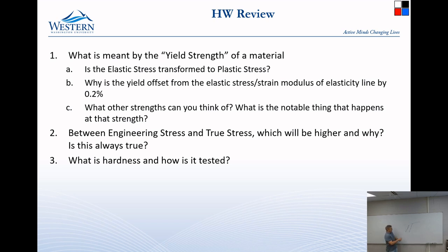That's right. Because in the book, these look like nice straight lines. In real life, they are not. In real life, it wiggles as it goes up here and different things happen within the material. And this is just saying, okay, we have now deviated enough from that nearly linear portion that we're gonna say, yes, at this point, we have moved into the plastic region.